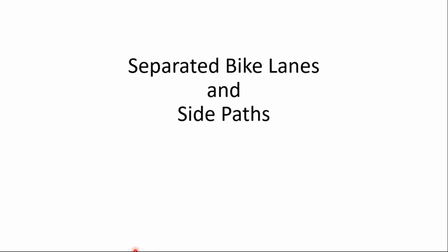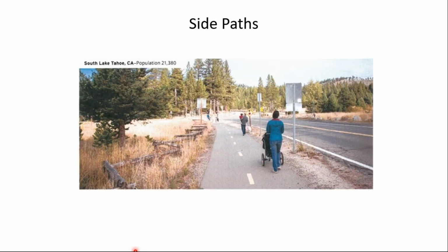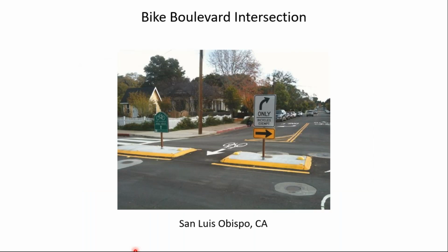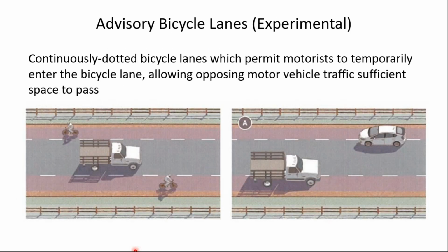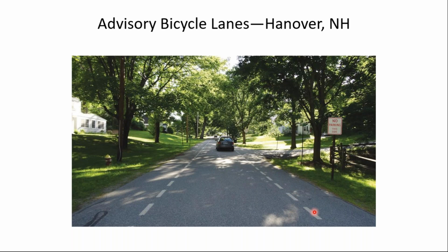Wonderful. I actually have a couple more. Okay. We have a question asking, is there a maximum ADT for bike boulevards and advisory bike lanes? Oh, great question. I'm not sure I've seen any, although I would add, pardon me for backing up again, that my personal opinion is that the advisory bike lanes are really most suited for what I would call low traffic volume roads.